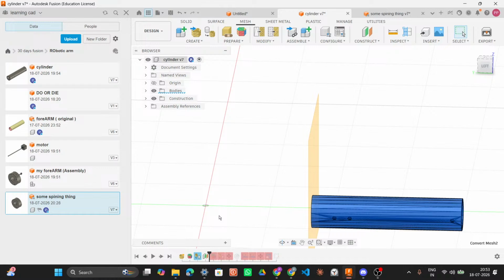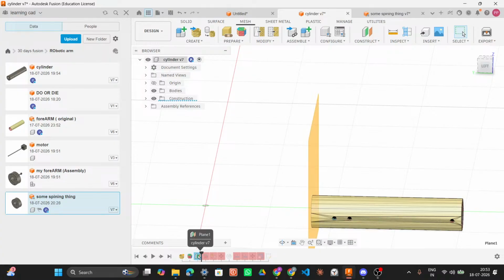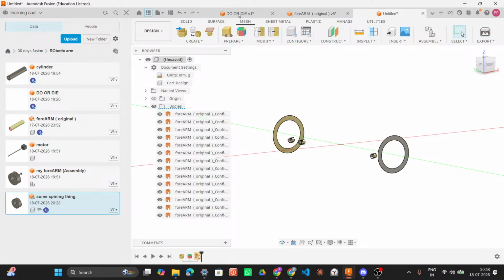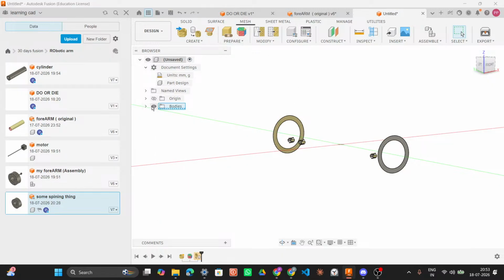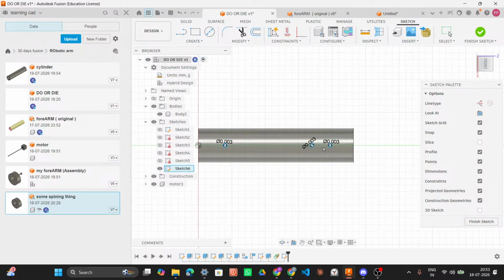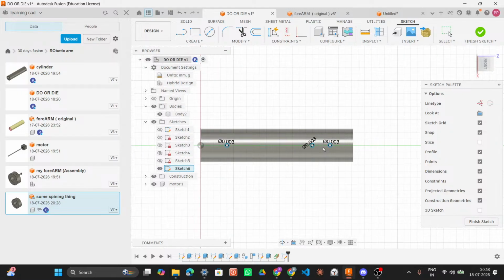But yeah, so from there, when I put that sketch on the end, I would just do a sketch and project in 3 points from the inner and outer circle, and then just do, what is it called in a sketch? A 3 point circle.